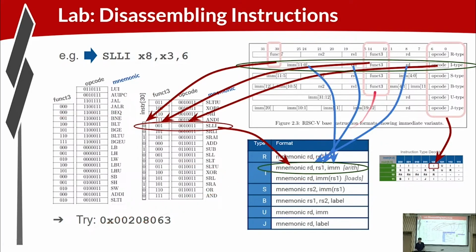And then we pull out the fields. So B-type, these are the fields. We pull out the RS2, which apparently is X2. RS1 apparently gives us a 1. And then this one's going to be source 1, source 2. It's always ordered destination register, source 1, source 2. Anything that doesn't exist is not listed. And then the immediate bits all are 0.